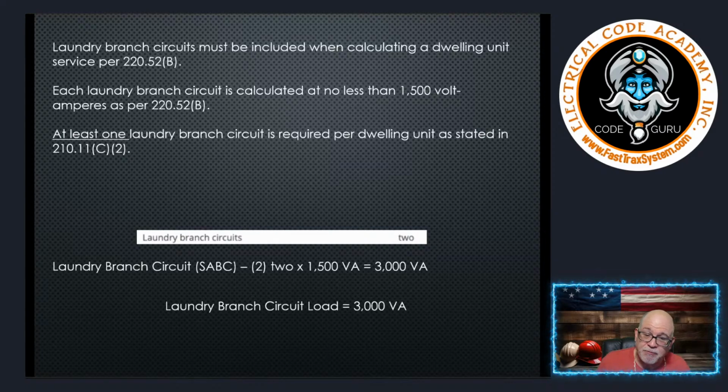Ironically, that's the same thing for cooking. I don't know if you knew that or not. I could have gas cooking and have no loads when it comes to cooking. I'm not forced to put a value in for cooking. So that's the same thing for the dryer. Now, if I do have the dryer circuit being installed and it's a 30 amp, then I have to take that into consideration. Hopefully that answered your question.